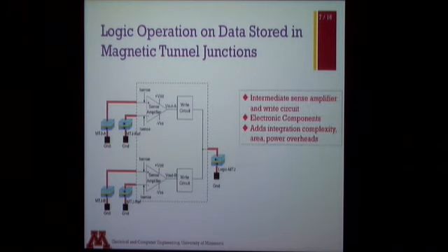So there are a lot of overheads. It is very complicated. And another subtle thing is that the resistance is not just read out and converted into current, it's converted into a bidirectional current. So a sense amplifier has to be designed in that particular manner. The more important and more serious implication that this is showing is that every logic operation comes with its own sense amplifier circuitry. Even though these data devices and this logic device look exactly the same, the logic capability comes with a lot of strings attached to it.